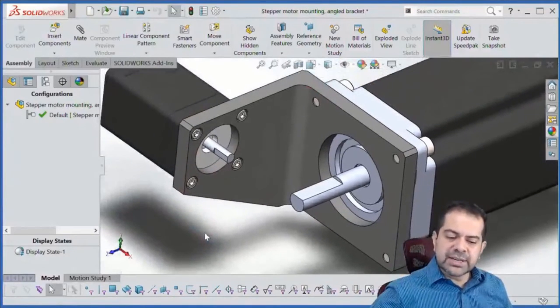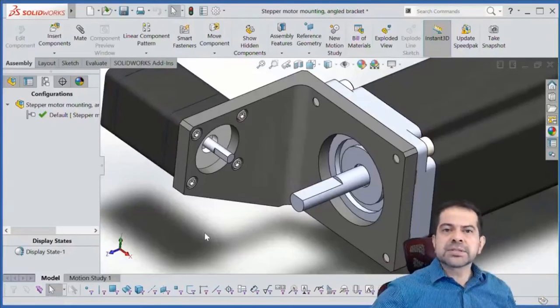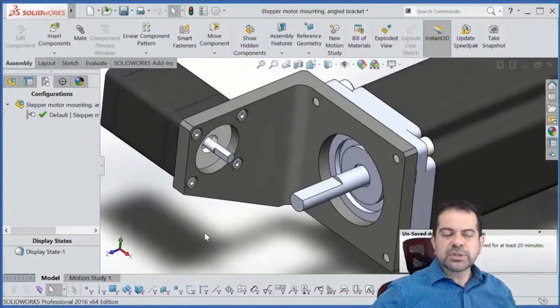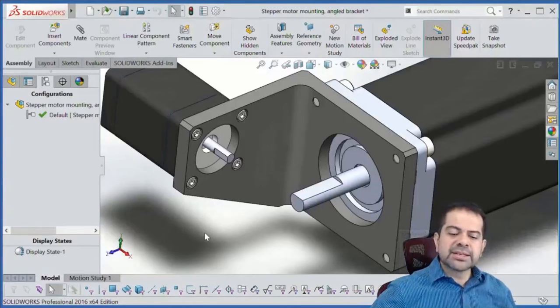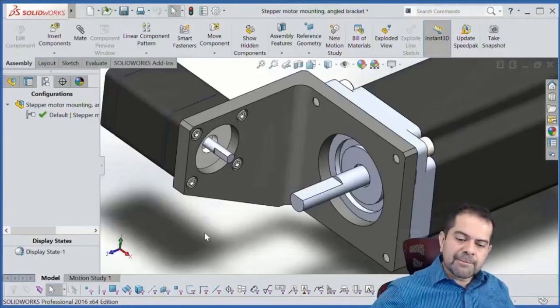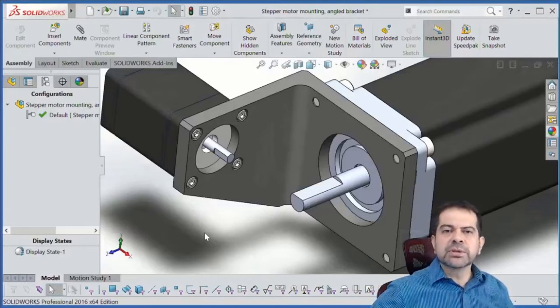Now, once again, they work in some cases, especially if you have the right torque, the right size of set screw, the right materials. You add chemical compound perhaps, or you have some other method to secure the set screw. In those cases, it can work. Pulleys, things like that, they come with set screws so that you can use this approach. Now, if you are designing something that has a certain level of vibration and shock, it's best to stay away from set screws. They will loosen up.